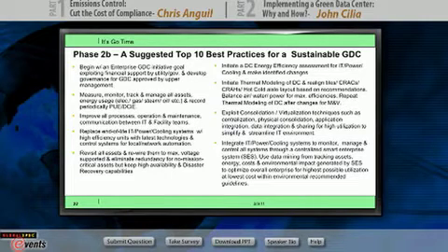For example, you can have a PUE, power usage effectiveness, that gives you the ratio between the total energy used for your site and the energy used for your IT equipment. It is one simple way to figure out something like that. And again, you have to track it and monitor that. You have to be able to compare month by month, for example, where you were and where you are after implementing a project, and that will be very helpful again to sell your upper management on the next step.